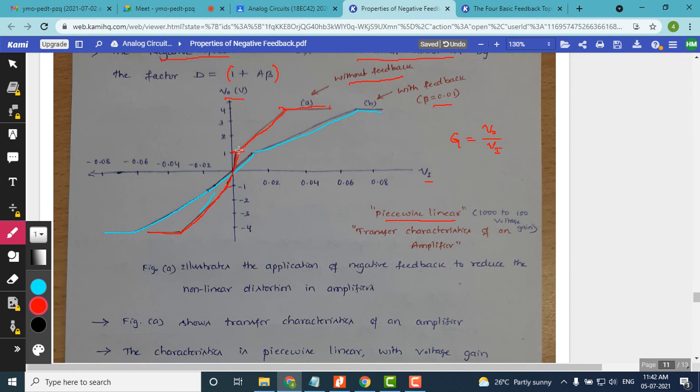see here. So, as I told you how to calculate voltage gain, just divide this voltage Vo by Vi, that gives you the voltage gain, 1 by 0.02, 2 by 0.04, like that, and this value, you can draw a straight line here, and approximately you can draw, I can show you vertically, you can draw downwards, and it may be 0.03 this value. Now you can calculate what is voltage gain, 4 by 0.03. Okay, that is how we can calculate the transfer characteristics gain value.